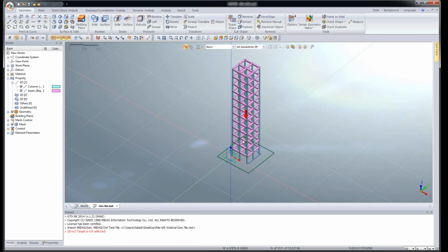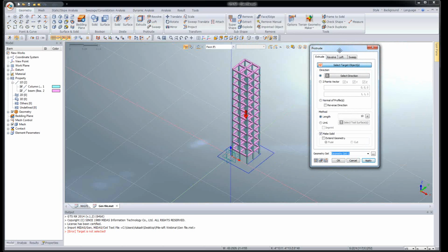Now I need to make my solid geometry. So just go to extrude. In the extrude option, whenever you want to select a particular type of element or particular type of curve, this is the selection filter. Just make it basic, so it automatically takes care of wire. A wire is nothing but a closed loop of edges. That is what a rectangle is.